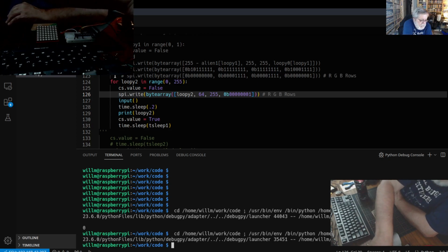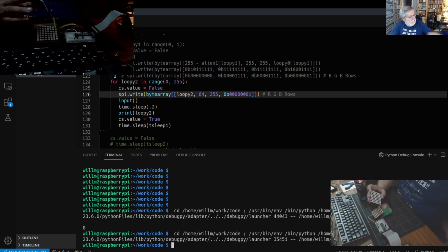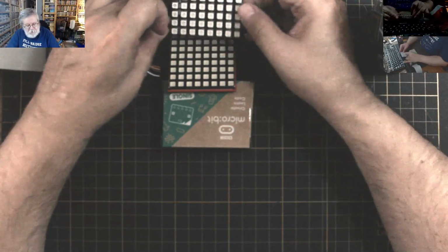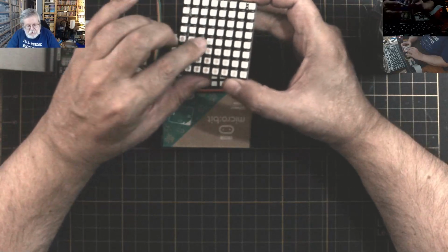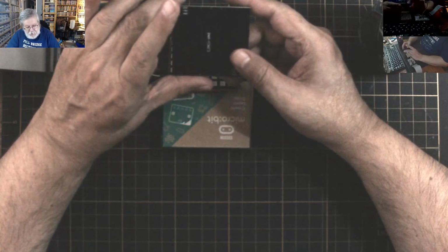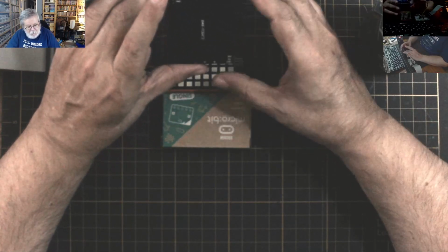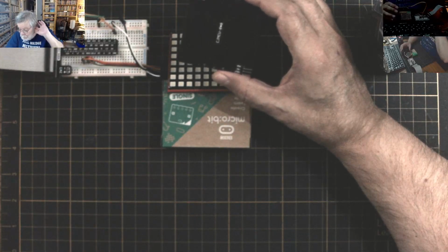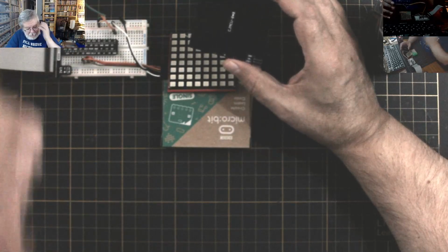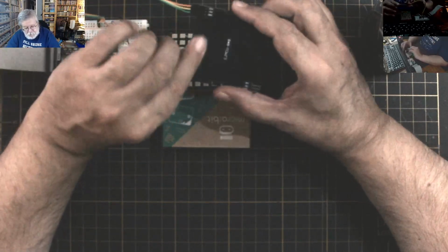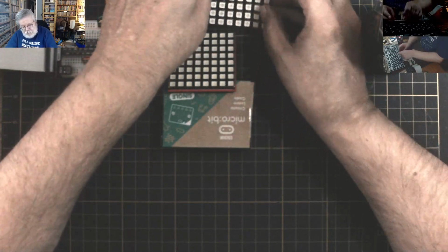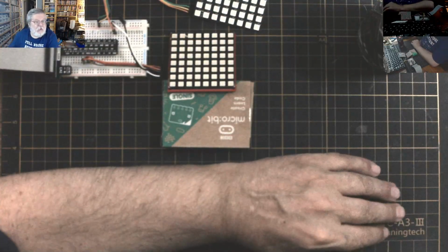Now, we have here this one. It's almost the same size, slightly bigger, but these are neopixels, right? They also run on an SPI system. Or actually, not even that as much. You don't really need SPI to actually run them. You just need a data pin. So currently I have this hooked up to the Raspberry Pi on the 5 volts, and I have the data pin on number 21. So what we're going to do here is we're going to go to a different set of code.